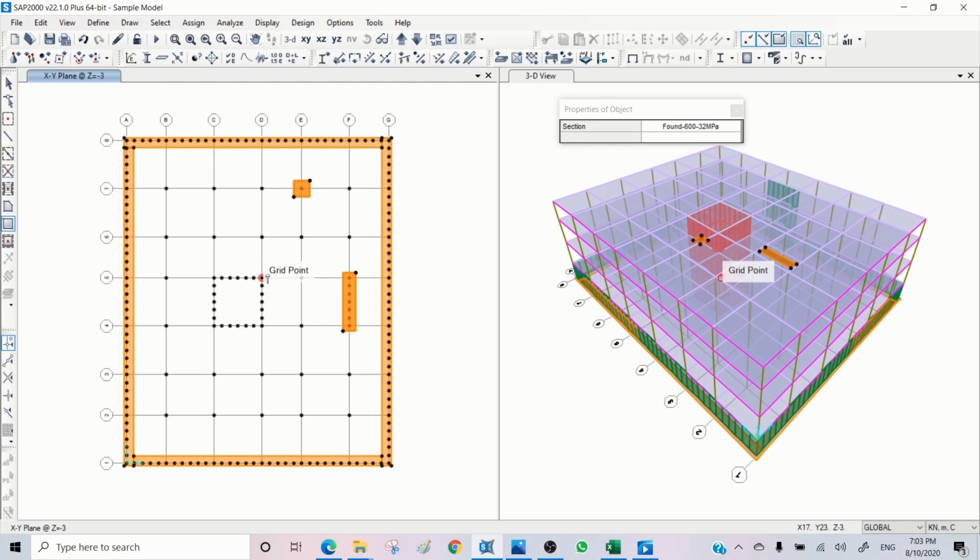So to draw the lift foundation, first, if it's important for you, you need to draw the lift pit. And lift pit generally is 1.2 meters lower than the basement level. And you just need to bear in mind that always shell elements will be connected from center to center, so center of thickness to center of thickness of element. But if you want to show it on top, there is no kind of rigid zone for shell.